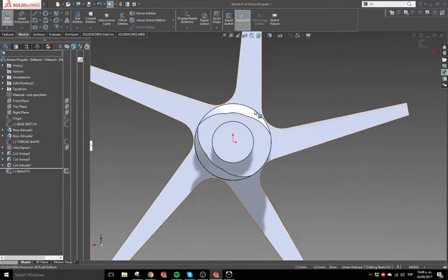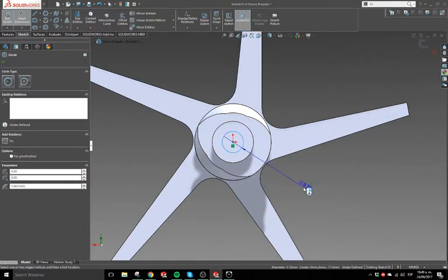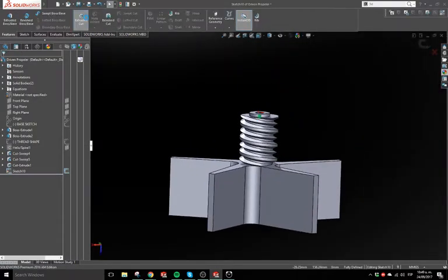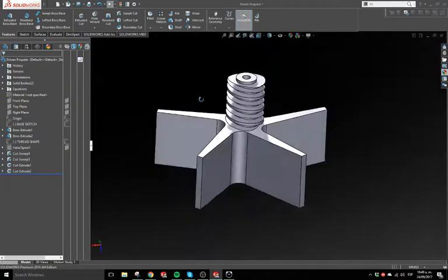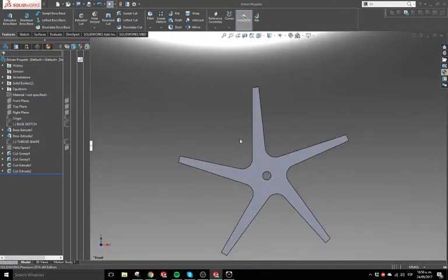And now this thing that goes in the middle, which is 3 millimeters, I'll put it by pressure, so I'll make it 2.9, give or take the accuracy of the 3D printer, so it should get in with a lot of pressure there. So now we cut, but this time inside. And here you go, we have the part. Now let me take a look at it and see if it looks kind of like the original one.